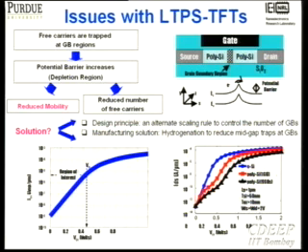In general, if I look at thin film transistors, there are several issues that I have to look at. On the right side, which is shown right here, is a transistor which shows a source and the drain of the transistor, using polysilicon channel material. If I'm using polysilicon channel material as opposed to crystalline silicon, there'll be grain boundaries, right? And what are those grain boundaries like? In general, due to these grain boundaries and having traps over there, my overall mobility is going to decrease, right?